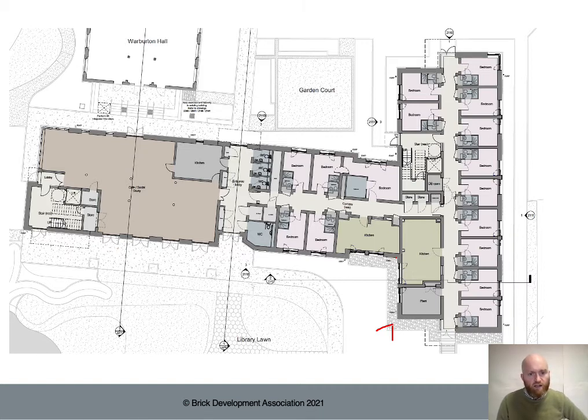Looking at the next section of brickwork into this corner here, well, that looks like it is probably a short return, so less than the 675. So I think what I will try and do is introduce a movement joint within that internal angle there. And again, hopefully we won't read that as anything hugely different from our normal bonded corner that we have on the other side.